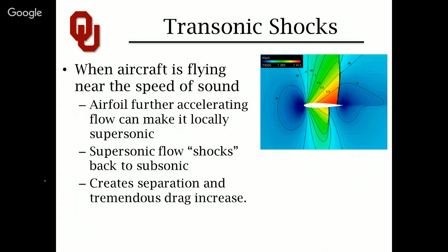But oftentimes around the engine nacelles on the top, perhaps around some vortex generators, winglets, some small locations of the aircraft will definitely generate small shock waves. And you tow them along with you the entire way during cruise if that aircraft is really pushing it in matters of speed. But what forms transonic shocks is when the airfoil, in this case only considering the airfoil, it's only two-dimensional, the airplane doesn't exist, it is only an airfoil.